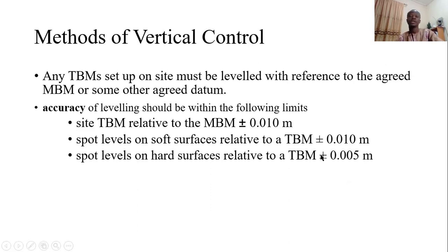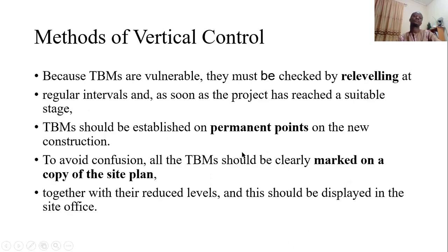Are you okay? The thing with the errors is that they compile, according to the accuracy of measurement. They do compile as you go. All right, because TBMs are vulnerable, they must be checked by releveling at regular intervals.